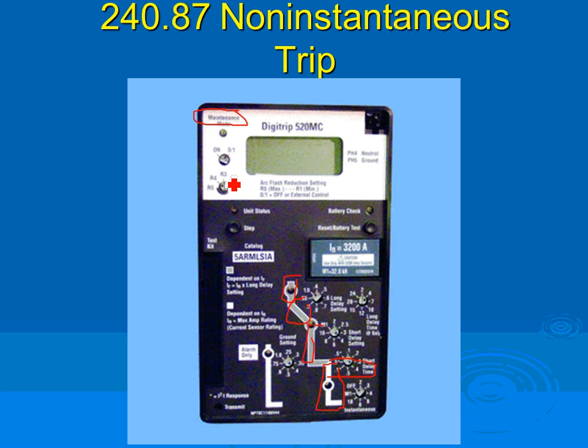So you go through all this, turn it on maintenance, work on it, and you reduce the arc flash from this amount when you put the instantaneous on into this amount. So you can survive the arc flash based on the PPE that you have. When you're done, while you're dressed up, you turn it back on so you can maintain the coordination, and you leave. So that's the maintenance solution.